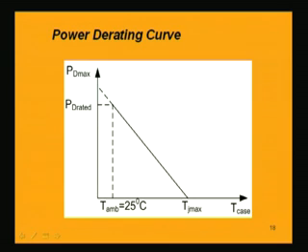That means the rated power of a transistor specifies the ambient temperature 25 degrees centigrade, which should be the temperature of the case. If we allow the case temperature to be higher than 25 degrees centigrade, then obviously the rated power will decrease.